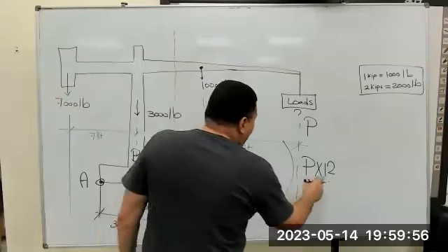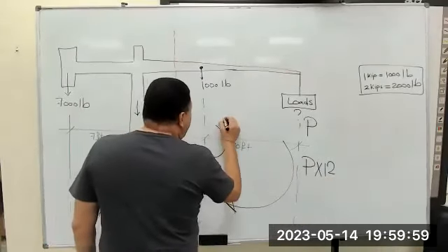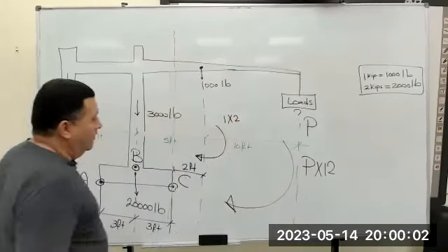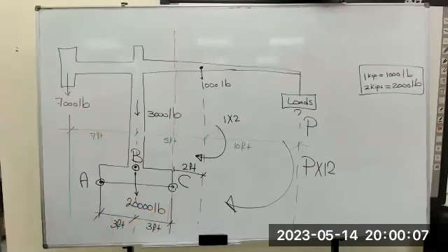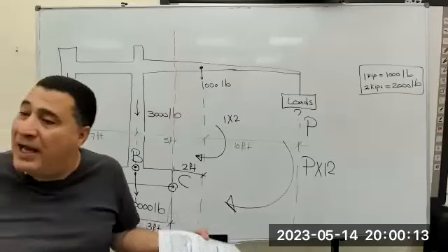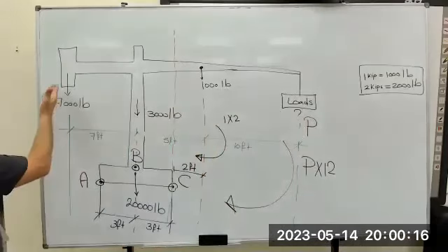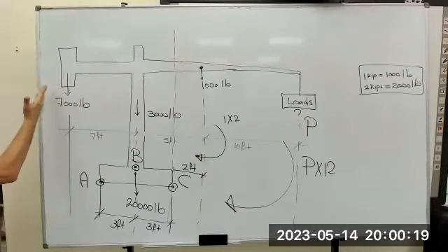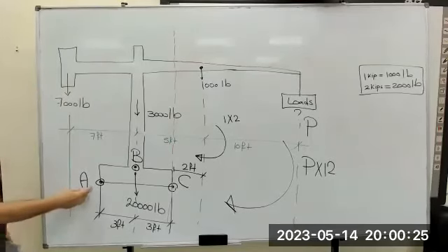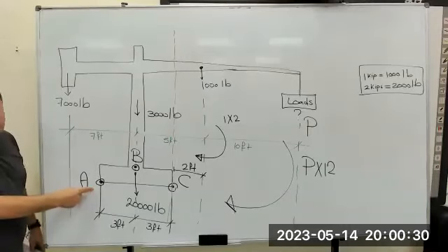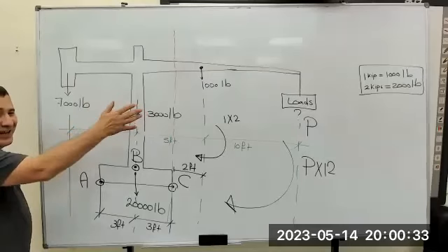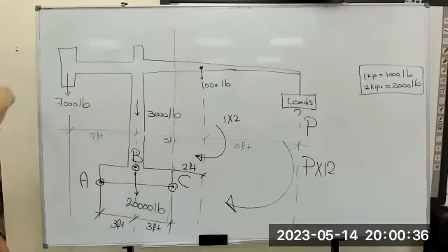Now LB multiplied by 12, plus the boom 1 kip multiplied by 2. Why 2? Because 5 minus 3, since our point is C. This comes from this side. To make it balance, we increase the counterweight up to a certain amount, then we stop. Why? Because if you increase the counterweight more than the limit, the system will overturn on this side.